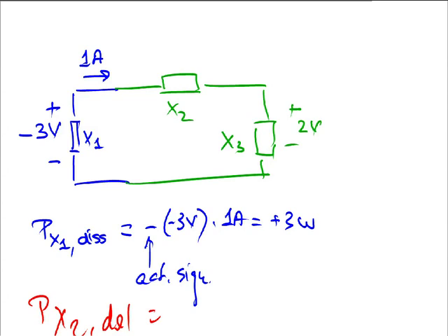Okay, yeah, we use Kirchhoff's voltage law, so why don't we do that? How do we apply Kirchhoff's voltage law? We draw a circle first, so like this. There is only one possibility here. And then when we write the law here, we enter on the minus sign, on the left side with component X1. I can't point to my screen here, doesn't help you, right? We enter the component X1 on the minus side of the minus 3 volts. So the first component is minus 3 volts. I draw this on purpose so clumsily so that you can see exactly.